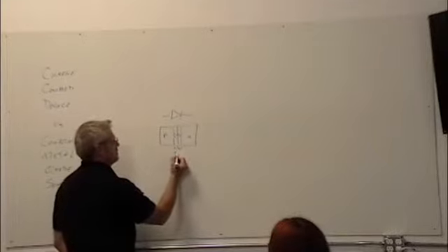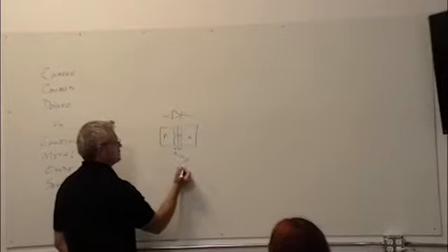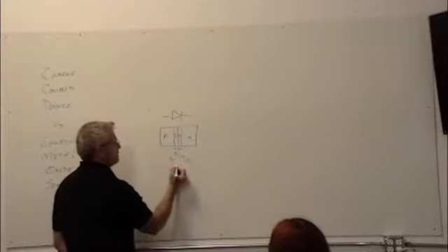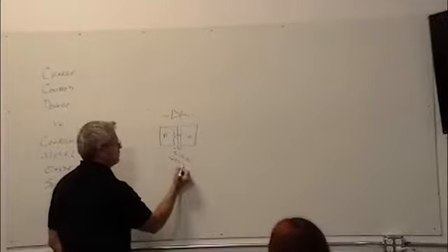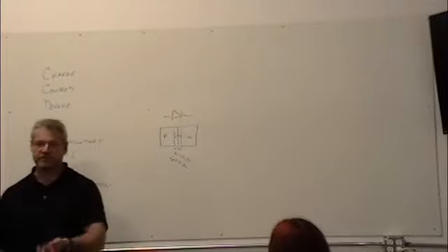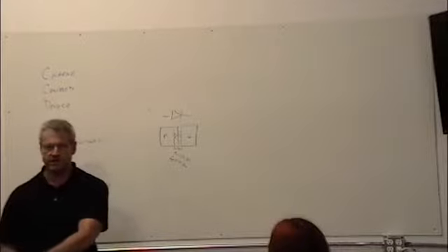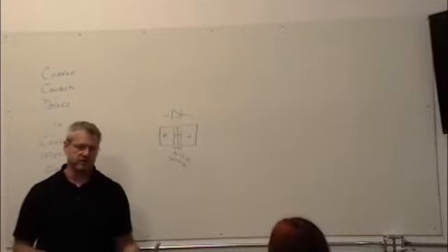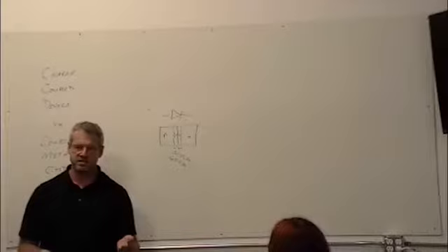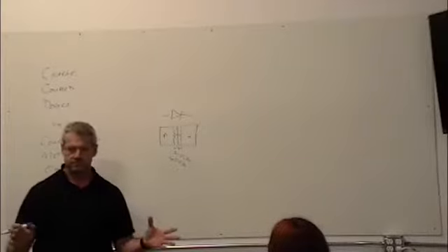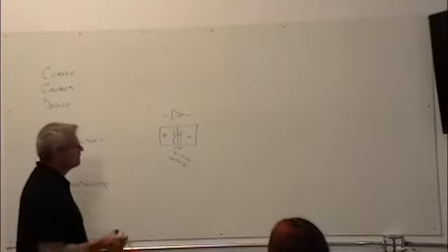In silicon, it's about 0.7 volts. In germanium, it's about 0.3 volts, which is why when you use a rectifier diode, it's got a 0.7 volt drop on it. They're usually silicon diodes. If you use some of the Schottky diode, fast-acting Schottky diodes, they're germanium. It's got a 0.3 volt drop on it.